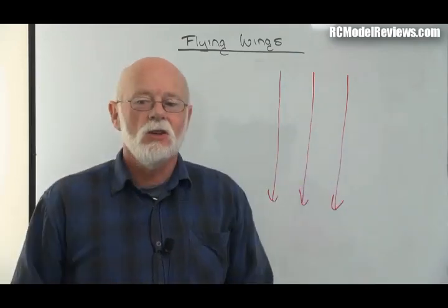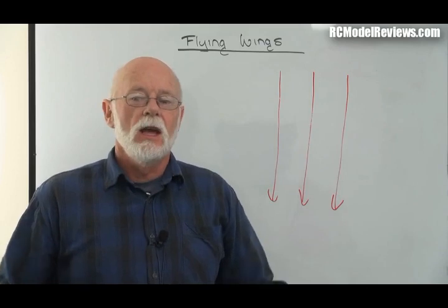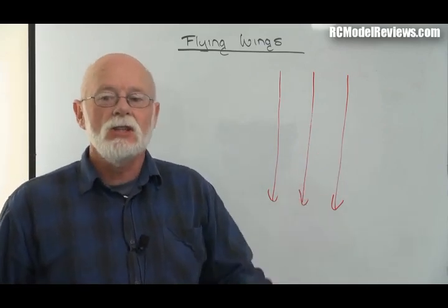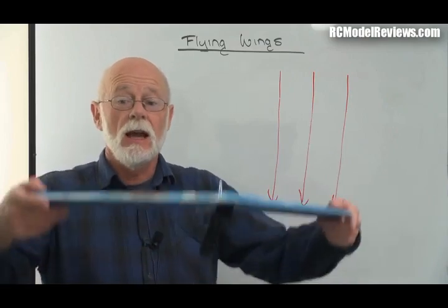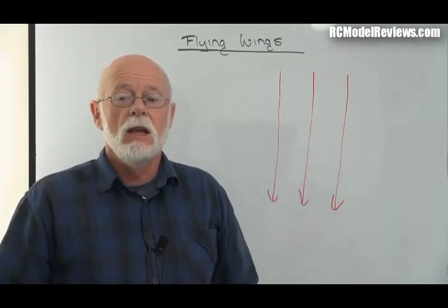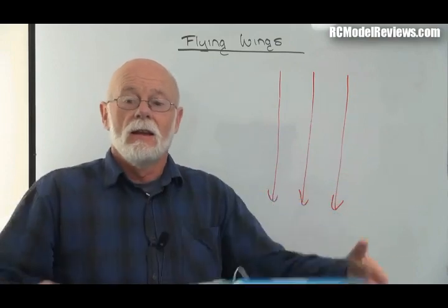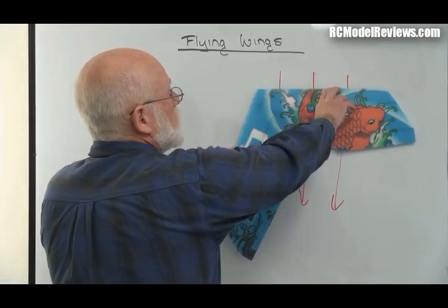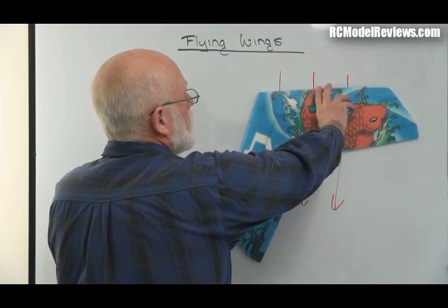This wobble, wobble, wobble thing is really common with swept flying wings flying FPV, because we have a situation here that's quite akin to mini quads or quadcopters, where you have a stabilization system. And if you don't get the gains right, you get oscillation. You know, you have too much P gain and your quad goes woo, woo, woo, woo, woo, like this. You have too much I and it goes woo, like that. Same here. We've got a corrective force. We've got feedback which is trying to correct the situation with the yaw.